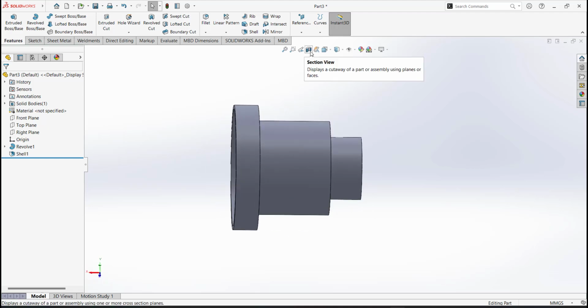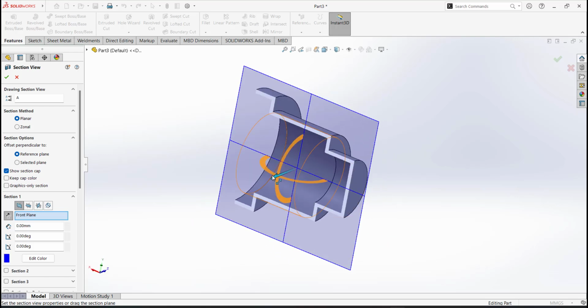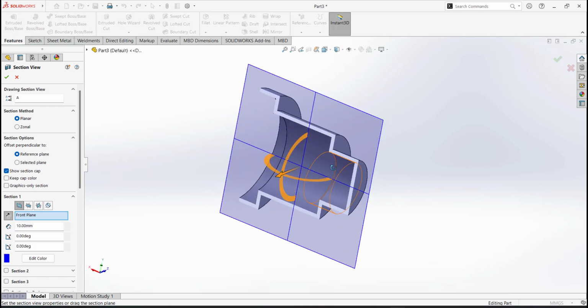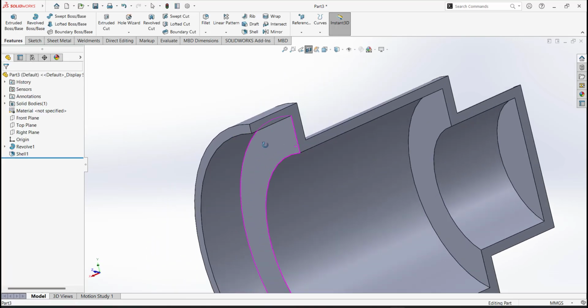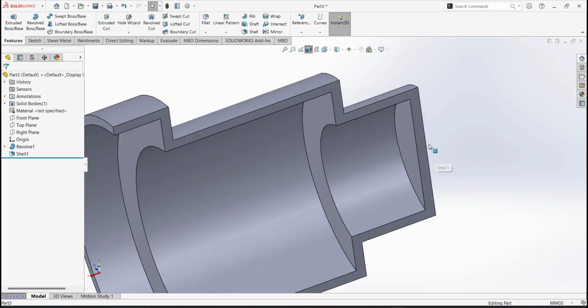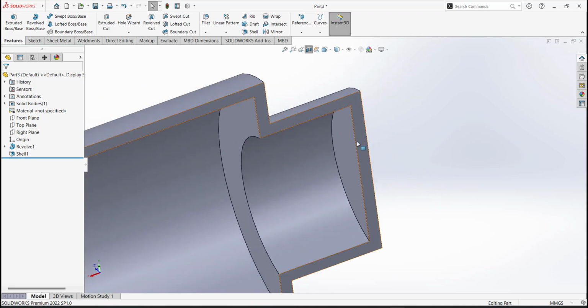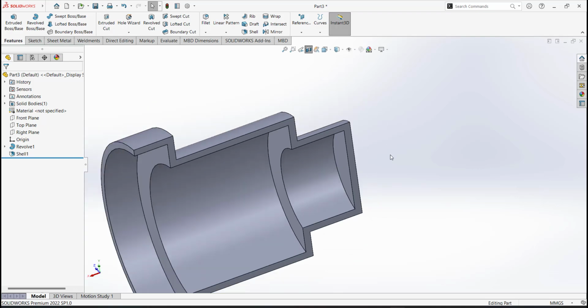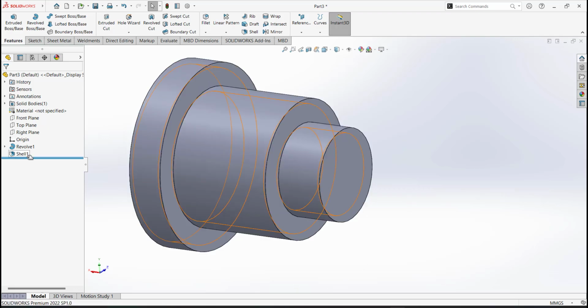You can take section view here. For section view, select this tab in view sketch heads up toolbar. Now you can see here this part has been made hollow. Say it okay. The constant thickness here coming is as 5 mm. Suppose I want to change the thickness here and provide one different thickness. So we will go for multiple thickness option. I'll put off the section view.